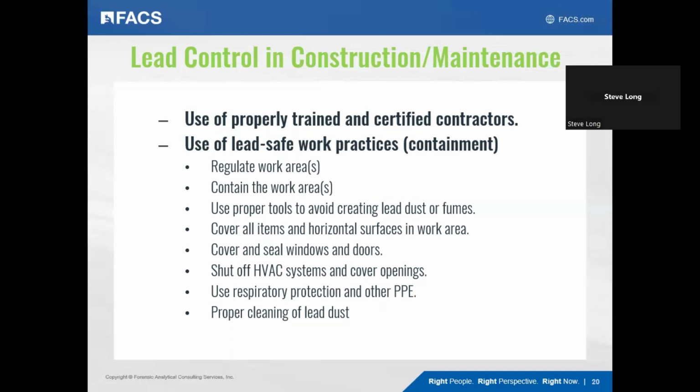So this is going to prevent not only contamination of the system, but potentially circulation of lead dust to other areas. For the workers, they use respiratory protection and other PPE, or personal protective equipment, to protect themselves from the lead dust while they're working with it. And PPE would typically include gloves, disposable shoe covers, and disposable coveralls.